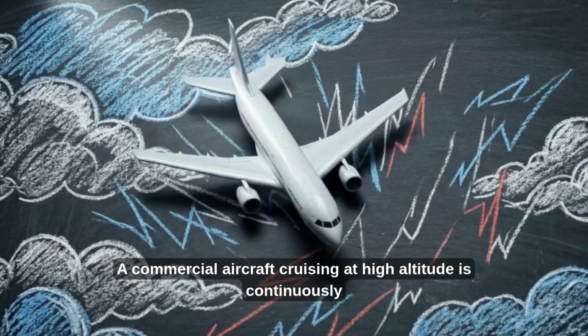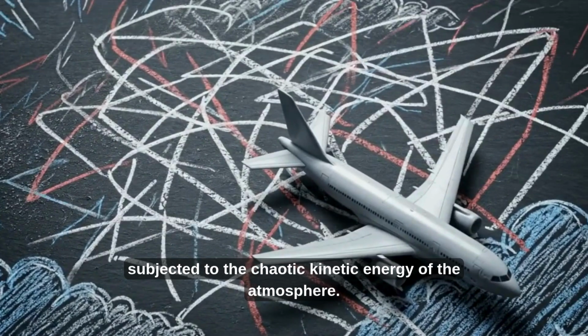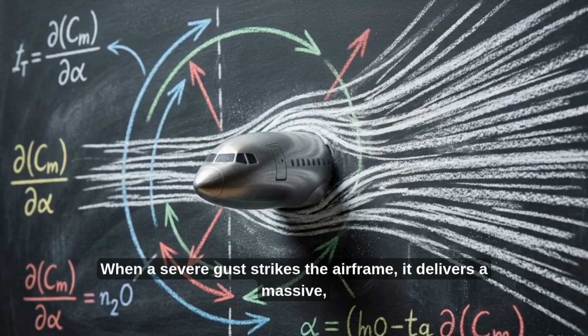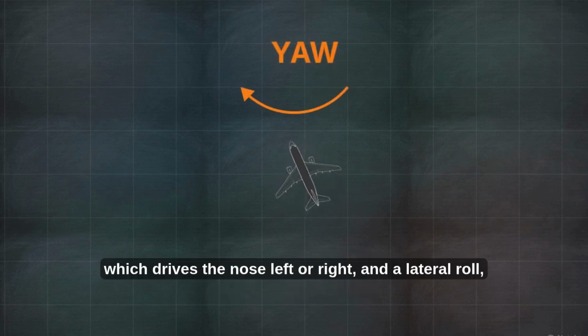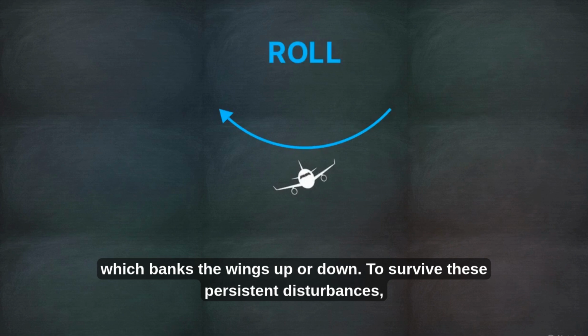A commercial aircraft cruising at high altitude is continuously subjected to the chaotic kinetic energy of the atmosphere. When a severe gust strikes the airframe, it delivers a massive, asymmetrical shearing force. This singular impact induces two simultaneous geometric disruptions: a directional yaw, which drives the nose left or right, and a lateral roll, which banks the wings up or down.